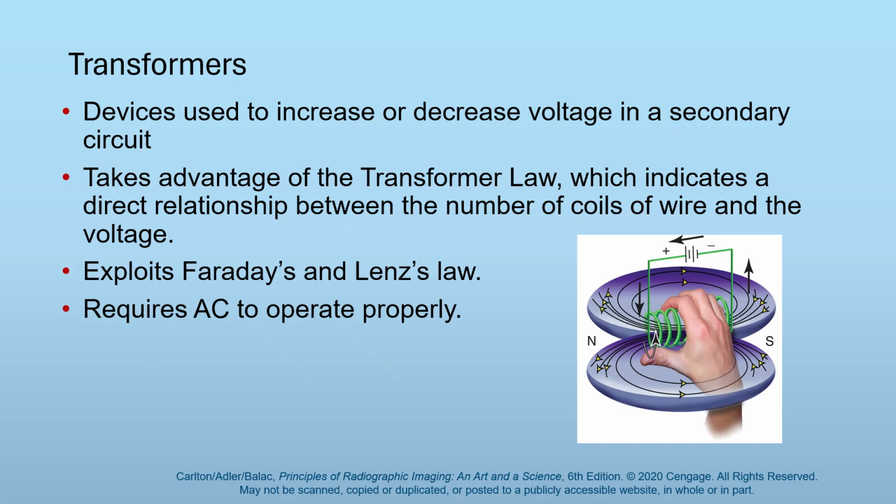You get a static magnetic field. If you connect a coil to a battery, you get a solenoid. You put an iron bar in the middle of the coil, you get an electromagnet. Static magnetic field, the thumb on your right hand, if your fingers are tracing the direction of current through the coil, either clockwise or counterclockwise, your thumb extended upwards will point to magnetic north.